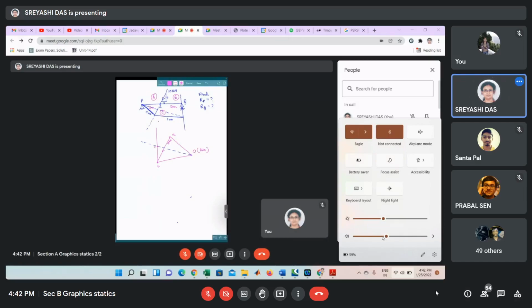So BC, in terms of magnitude and direction, will give RQ. BC, you see, it is upward, B to C. So here also the reaction will be upward. And C to A. This is like this, C to A. So here also, if you draw using set square a line parallel to the CA here, then it will give the reaction at P in terms of direction also.